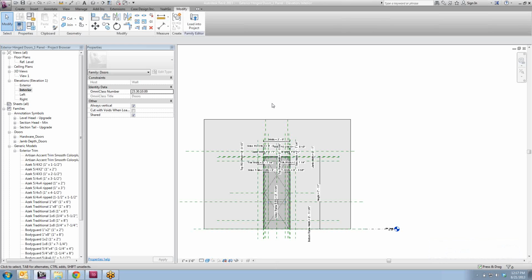Well, actually, I think the way it is now, are those two walls joined together in Revit? Are they effectively one monolithic wall as far as Revit is concerned? They're two. It'll be two, but you could join them together. Actually, you would want to join them together so that the opening cut for the door propagates to the joined wall. Would they be in different work sets? Yeah, I think you can join two things from separate work sets. Different phases? I think so.